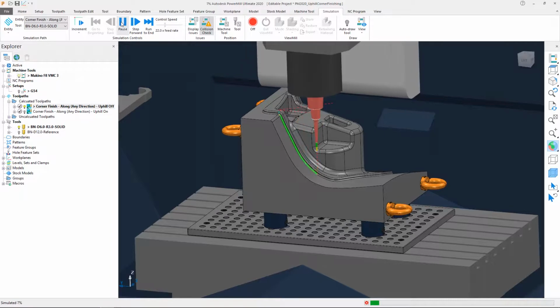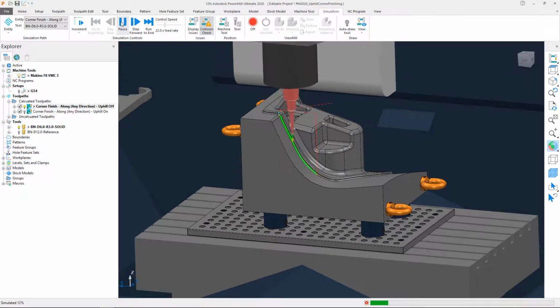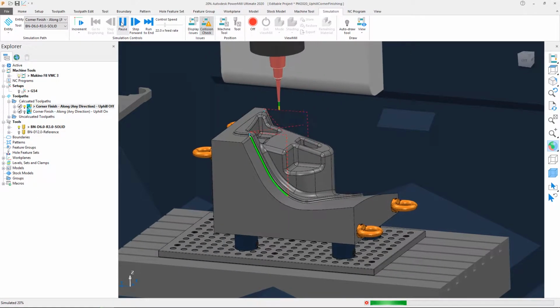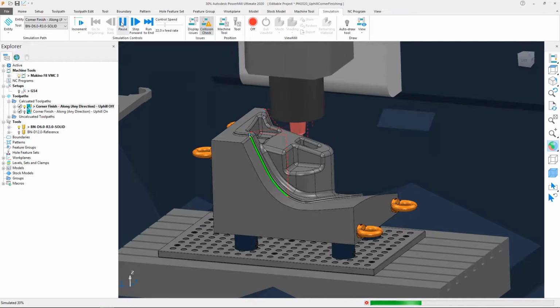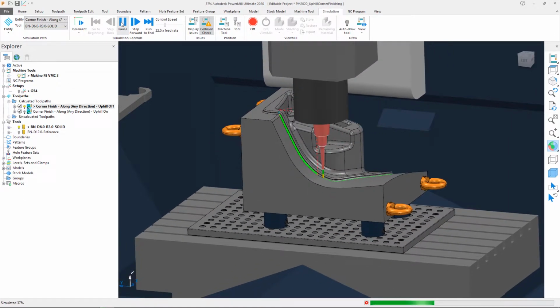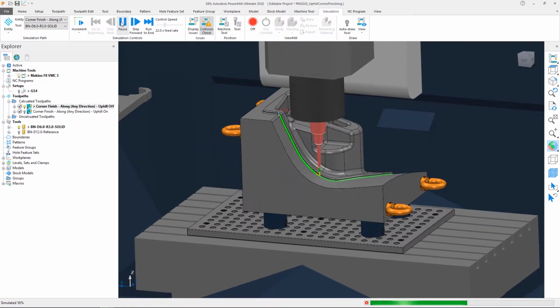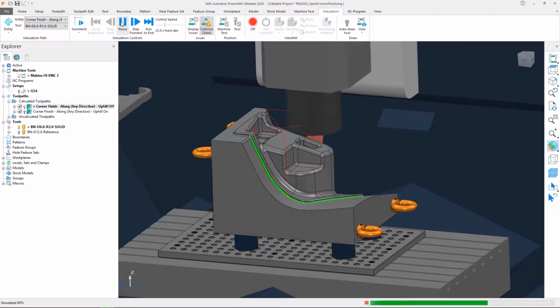We can see that when the toolpath engages the steep regions, the tool is moving in the less desirable downwards direction, even though the cut direction is set to any. As mentioned before, this could induce tool vibration, so it is likely that we would have to edit the steep segments in Powermill 2019 using the reorder option to reverse their direction.